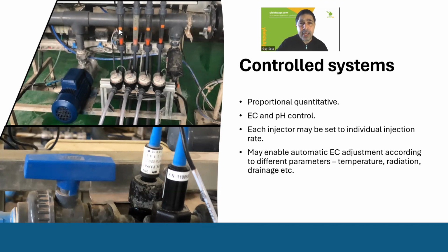Okay, you see here, you have flow meters where you can adjust the flow rate of each injector. Right now, it's very important, because this is a machine, this is a robot. But these flow meters are usually mechanical, which means that in the configuration of the system, you have to set up the right flow rate.